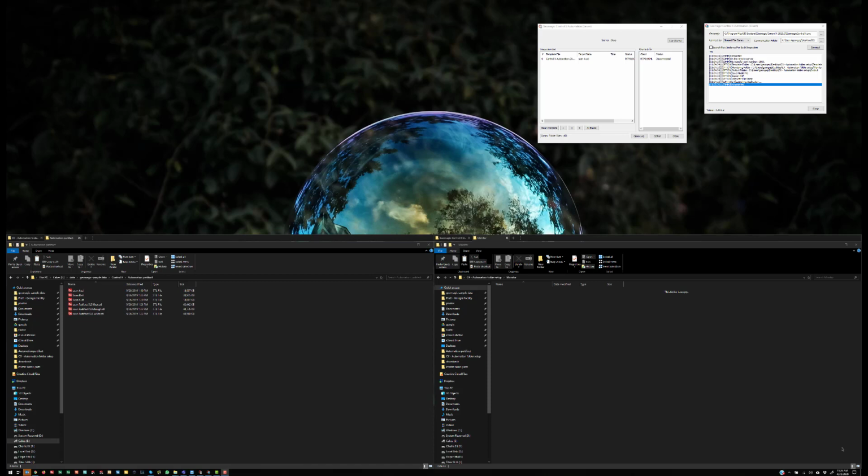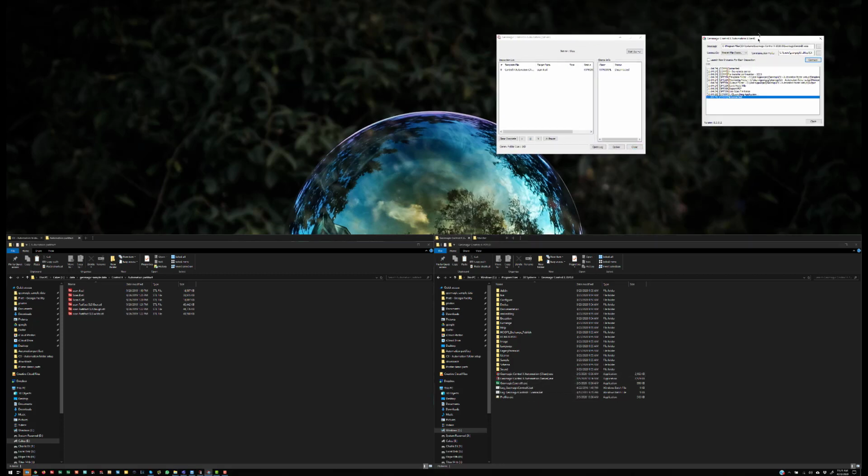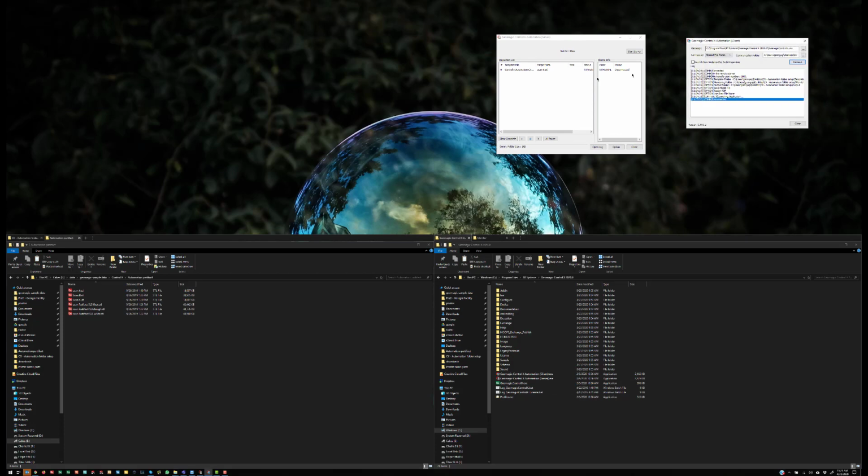The way you set up an automation server is you navigate in Windows into the install directory here. So program files, 3D Systems, Geomagic Control X. In that folder, you have 2 files, an automation client and automation server, which I have open right here on screen.